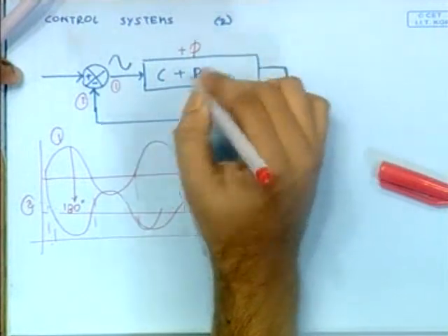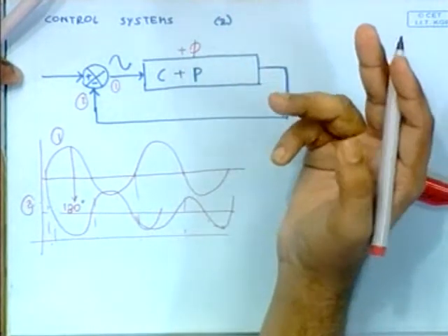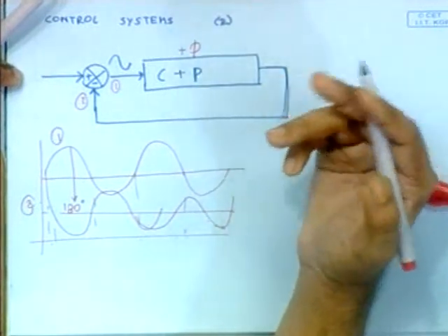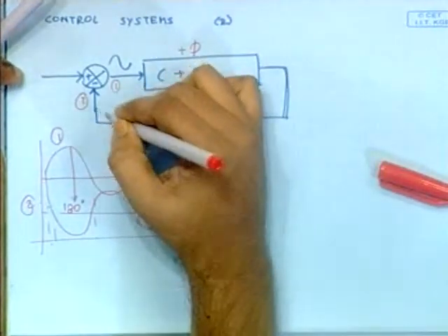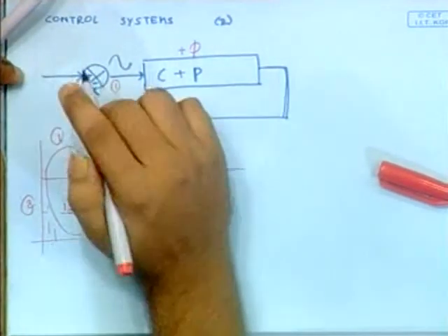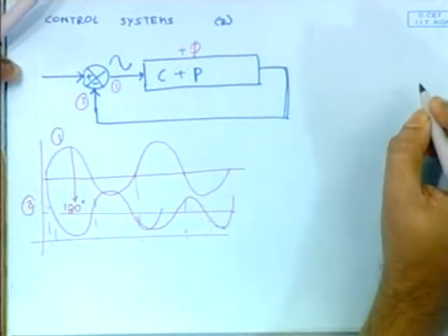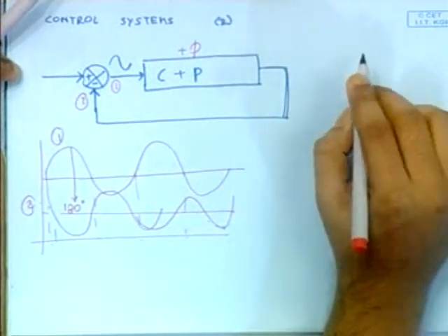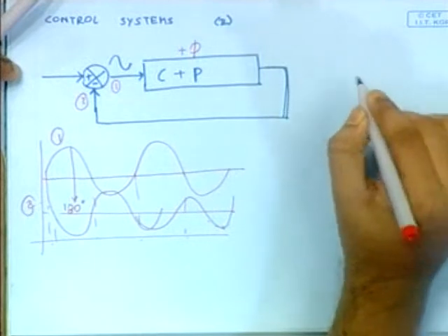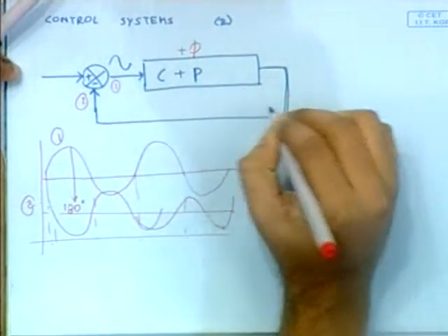noise. So if you take the transfer function of this entire thing, there will be 2 parts, your magnitude and phase. When you consider the phase, this much phase will be added to 2. You must ensure that this phase does not add up to 180 degree. So suppose this phase